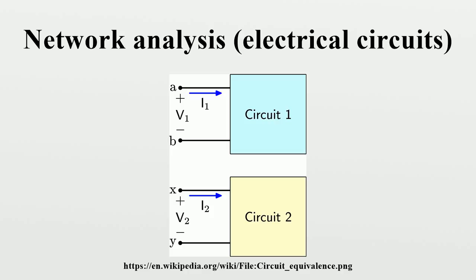The above is a sufficient definition for a one-port network. For more than one port, then it must be defined that the currents and voltages between all pairs of corresponding ports must bear the same relationship. For instance, star and delta networks are effectively three-port networks and hence require three simultaneous equations to fully specify their equivalence.